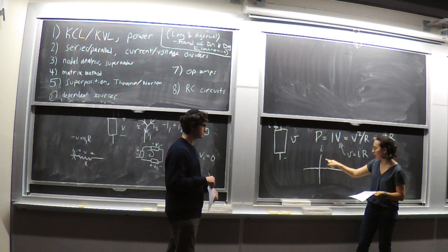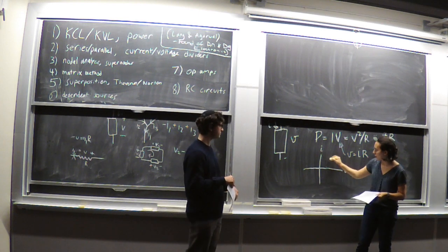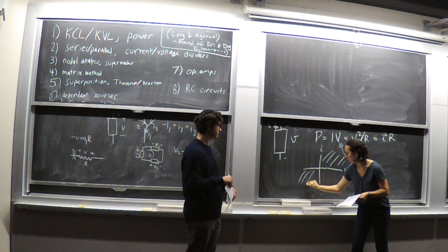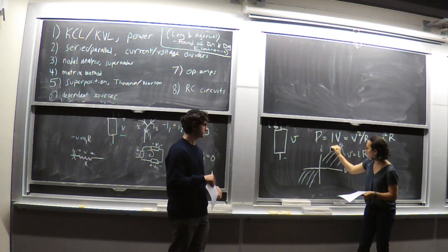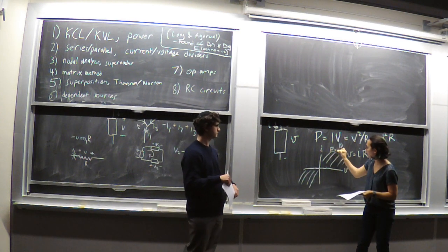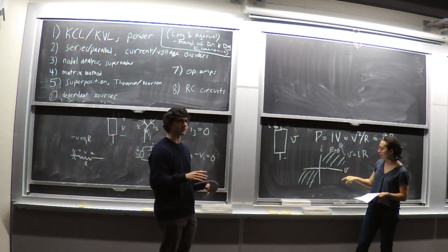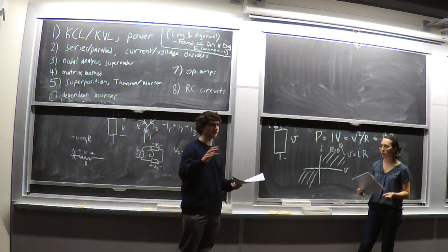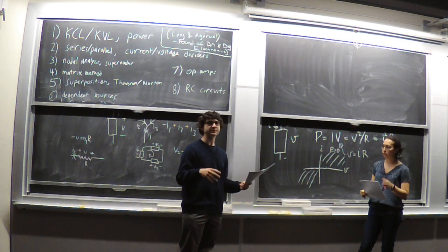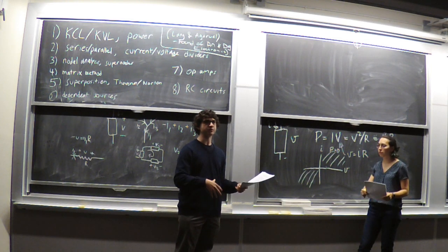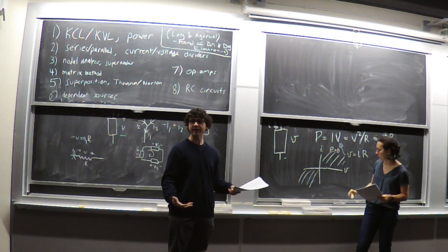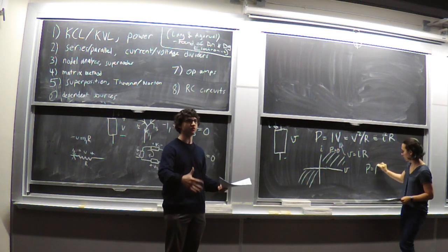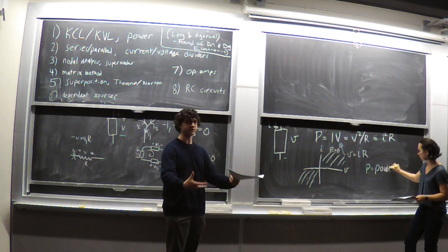So this would occur if I is positive and V is positive. So that would be these two quadrants where power is positive, meaning it's delivered to the device. Right. And the way to think about it is I times V. We always say it equals power, but does that mean power supplied or power consumed? I times V is the amount of power consumed by a device. So if you get a positive value, it is consuming power. If you get a negative value, well, what does it mean to consume a negative amount of power? It's the same thing as supplying power.